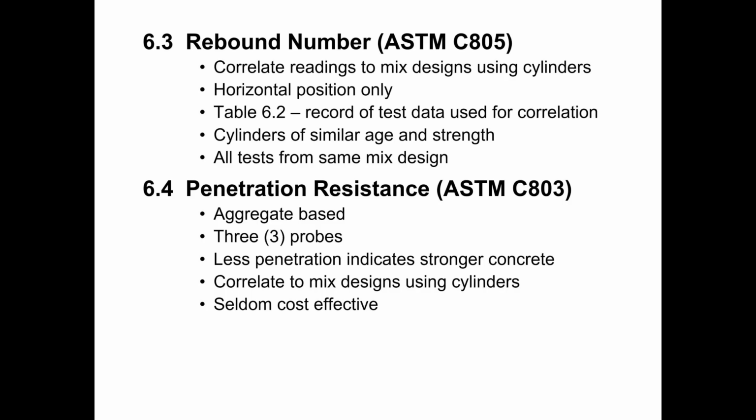We do have to do correlation testing for penetration resistance. So we should do a correlation curve if we're going to be using the penetration resistance method as the determining factor for when we can strip concrete.